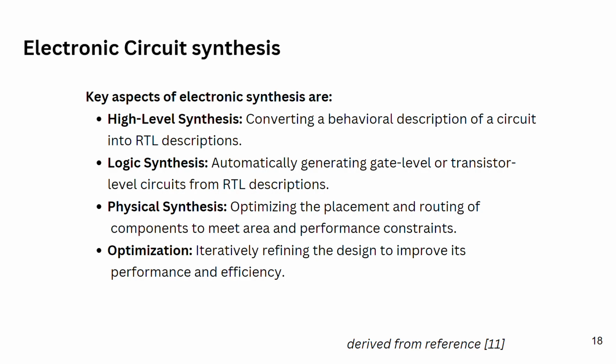Some of the RTL design tools are synthesis tools, simulation tools, and verification tools. In synthesis tools, the RTL code is the input, and we produce a gate level synthesis as the output. The simulation tool allows the designer to test the RTL design using input stimuli and observe the output response to ensure that the chip behaves as intended. The verification tool checks the design correctness and completeness, and also includes formal specifications or formal verification.